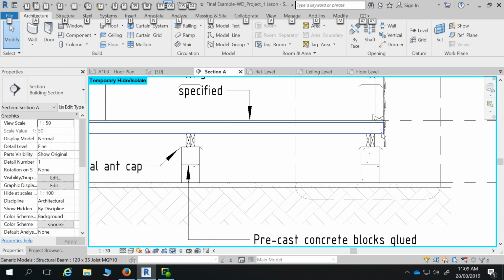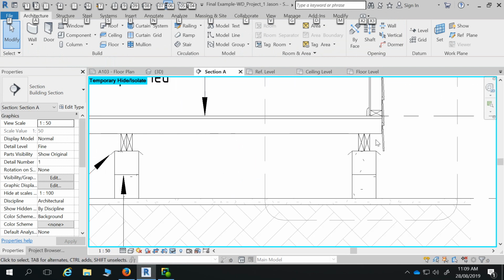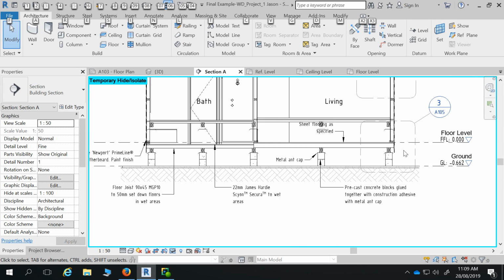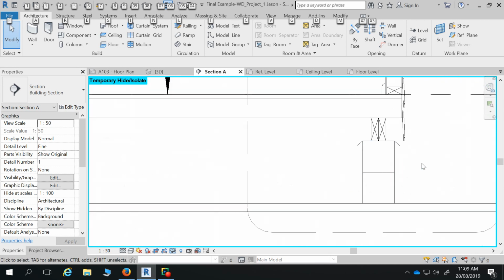So to pull the cladding down on the outside and protect this, we can actually pull it all the way down close to the ground if we want, because it's actually not timber, it's a compressed sheeting, so it's got cement fibre in there. So that's totally fine. And what would happen really is there would be a subframe set up that would be suspended from this bearer and joist and come down the inside here to stick the cladding on.